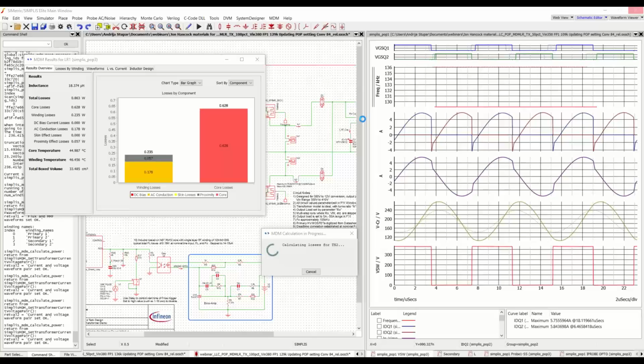We had another question come in. How do you calculate the inductance of the inductor and transformer? We calculate it based on a reluctance model of the core. So we would divide the core up, and for each core shape, we have our own model of a magnetic circuit or a reluctance circuit.